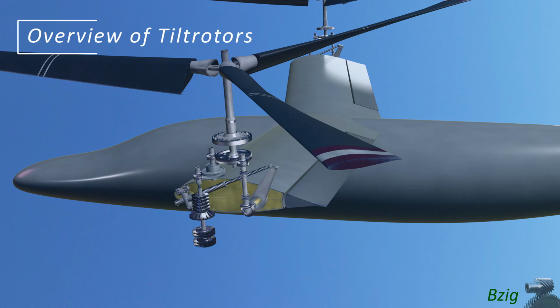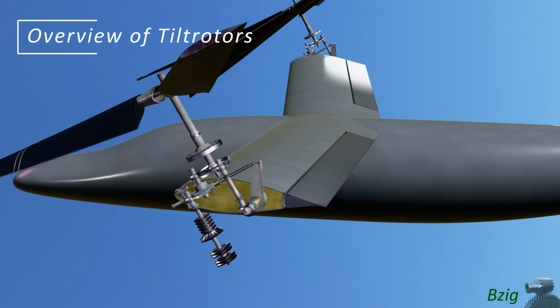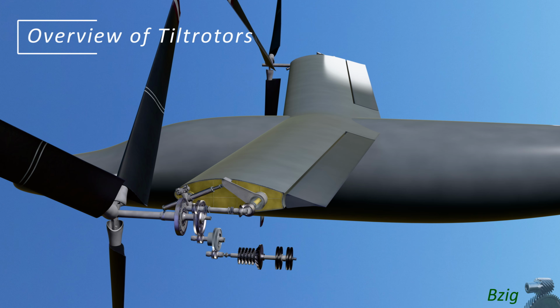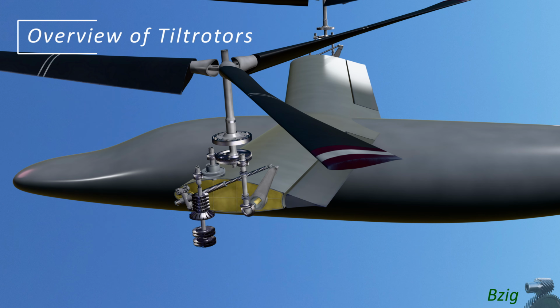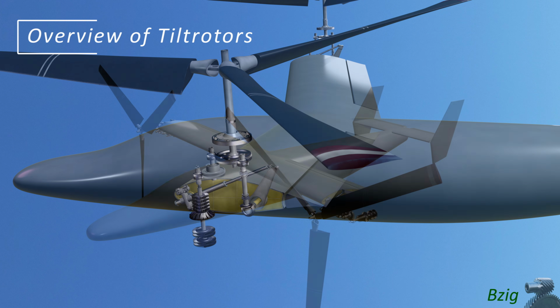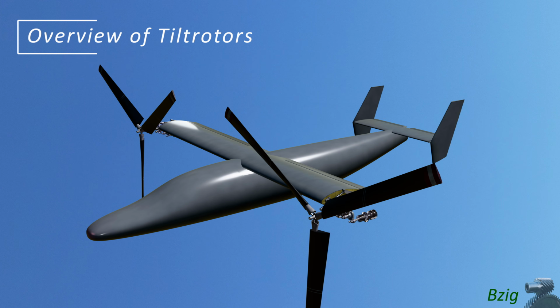The process of transitioning from thrust-borne to wing-borne flight takes about 15 seconds. It takes slightly longer to convert the other direction. Deceleration from approach speed to a hover might take maybe a minute or so, depending on how aggressively the pilot maneuvers.